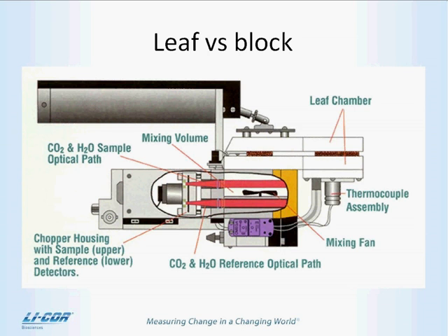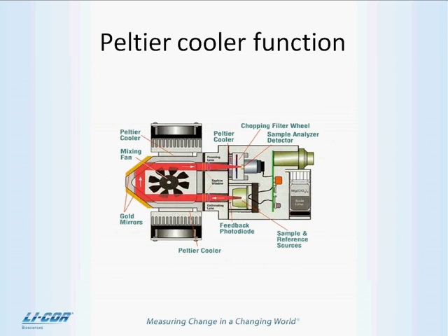The next thing to keep in mind is that the LI-6400 XT sensor head has some Peltier coolers. They're little thermoelectric coolers on the side of the sensor head that are used to raise and lower the temperature of the instrument block. They're just little ceramic elements with electric circuits inside. It's kind of like the radiator on your car. If you send the current flow in one direction, you heat the element. If you send the current flow in another direction, you cool the element. And that heating or cooling is transferred to the block and therefore to the air inside of your leaf chamber.